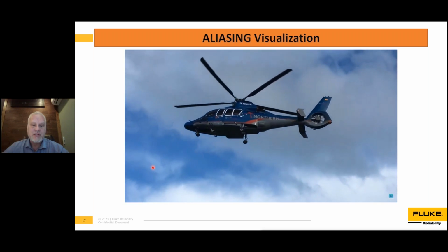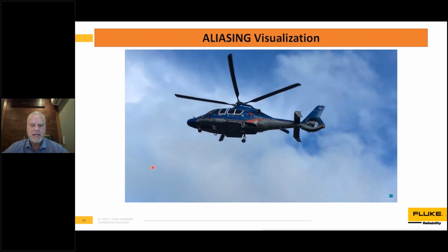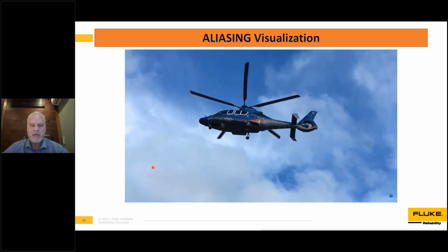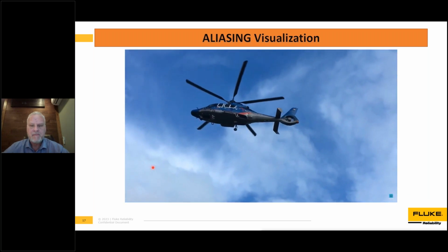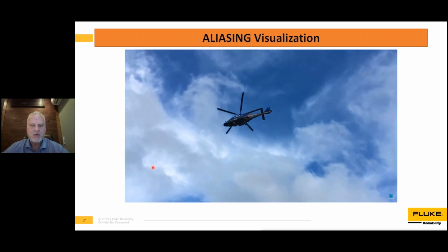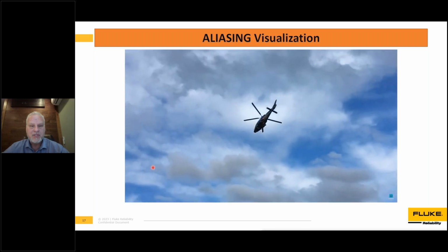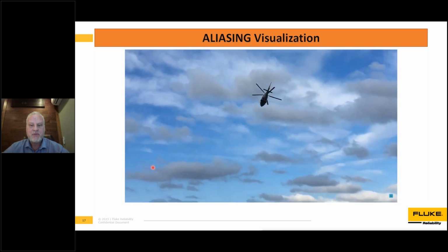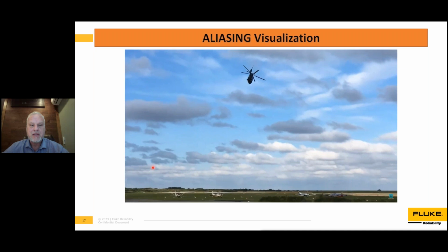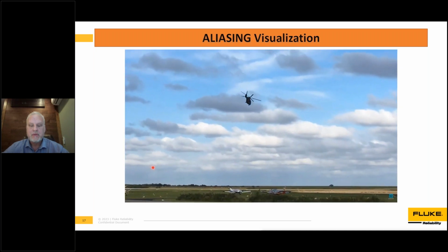If we allowed this in a vibration data set, we would see a very large peak at zero RPM. That would be meaningless. Again, it creates false frequencies that have nothing to do with the actual running condition of the machine. And for us, it would lead to false diagnostics. So we have to prevent this kind of alias signal from getting into our data. Super important.